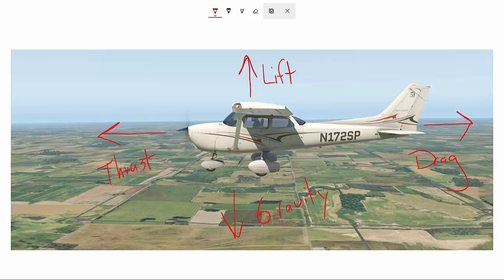We want it to return to the position that it started out in in order to make it a safer aircraft and an easier aircraft to control and fly, because we're largely using these for training new pilots and for just enjoying simple flight. We're not cranking and banking, we're not flying upside down, anything like that. Aerobatic aircraft, on the other hand, are typically pretty unstable. They're harder to fly in the sense that you have to be hands-on controlling it all the time.